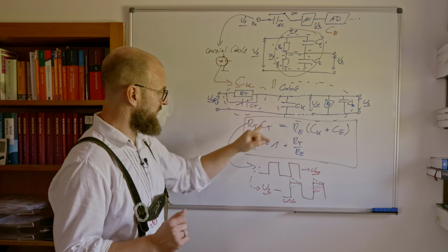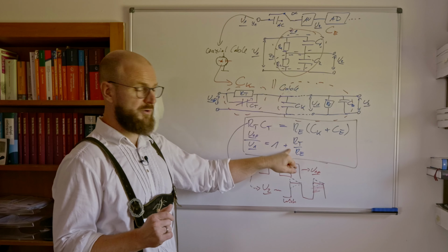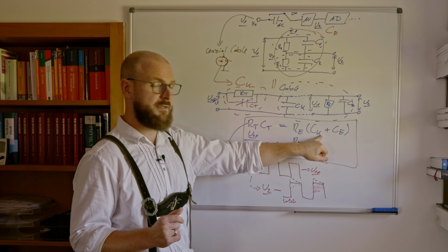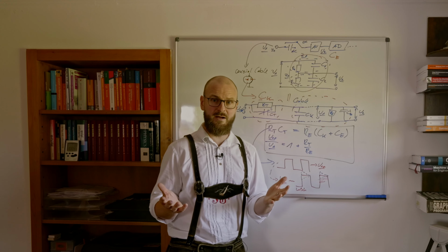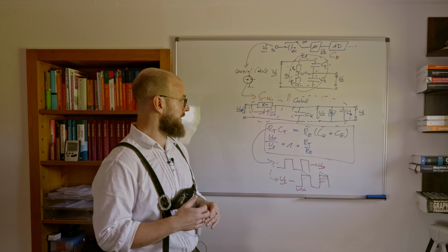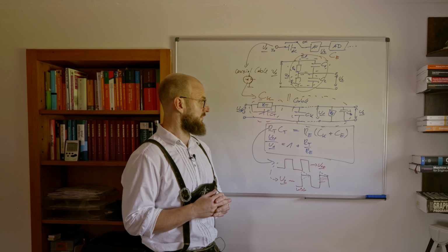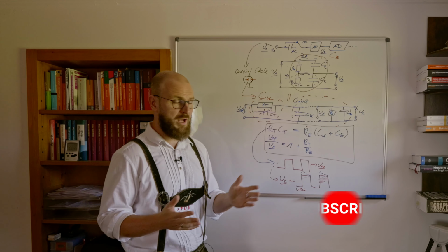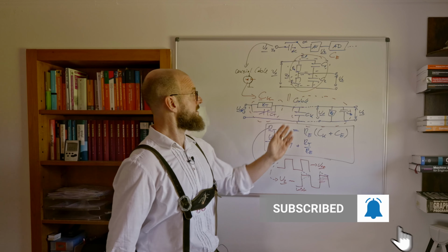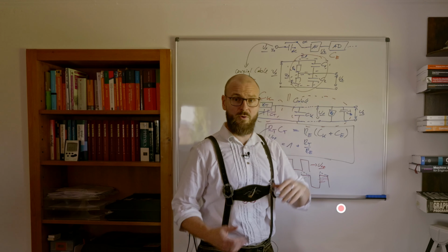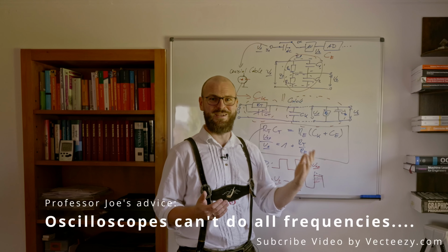So we have to deal with that. Ideally by knowing about your resistances, about your ratios, and about your capacitances. And at the same time doing the adaption via a real measurement, via a probe signal, which gives you an insight into the frequency dependence of your signal itself. When doing so, you can be sure to record the right signal and to record the right stuff using an oscilloscope to be dealt with by an analog digital converter, which we will talk about in the next chapter.